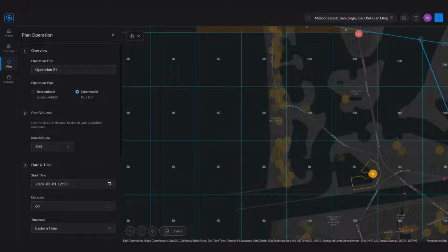And then, the first thing I need to do is hit my drop down and create my operational area. I'm going to create a rectangle. You will see my cursor has changed to a crosshair and will now allow me to draw a rectangle around the area. If you'll notice, I'm going to encompass two different airspace flight heights, both a 50-foot and a 100-foot flight height ceiling.